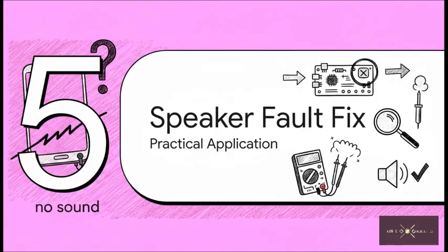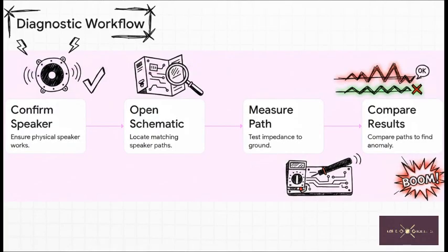All right, let's make this real. Section 5. Practical application. Speaker fault. Let's take all of this awesome theory and drop it into a real-world scenario. A customer walks into your shop, hands you a phone, and says there's absolutely no sound coming from the speaker. Let's fix it. Step 1. Always confirm the physical speaker component itself is actually working before you go blaming the motherboard.